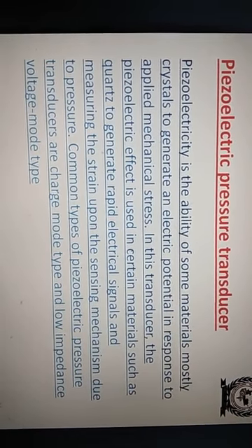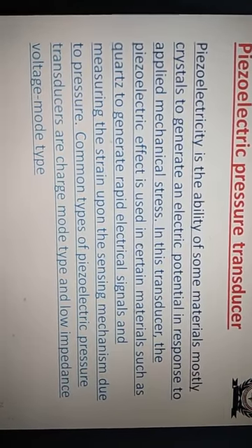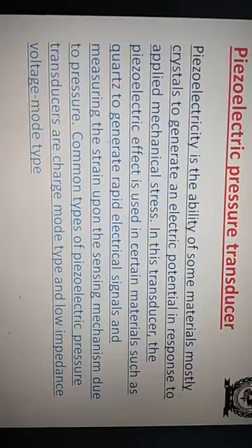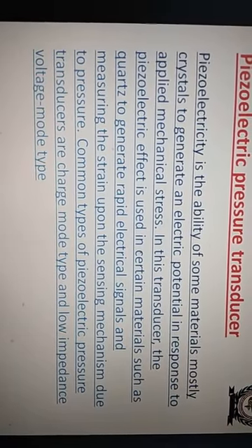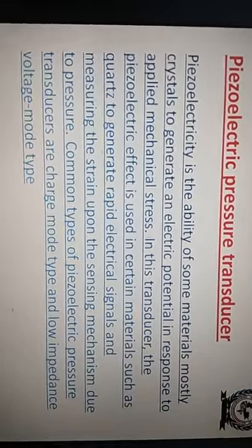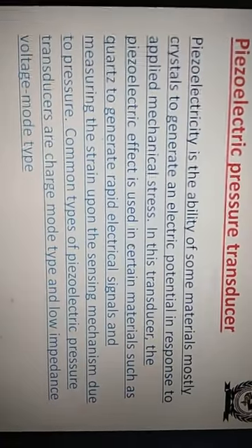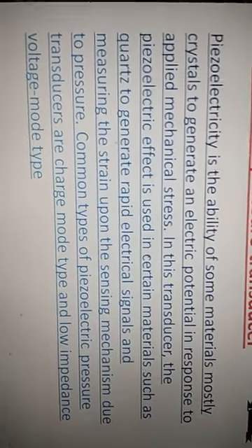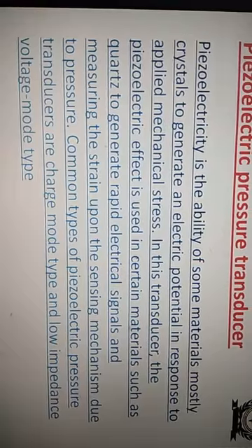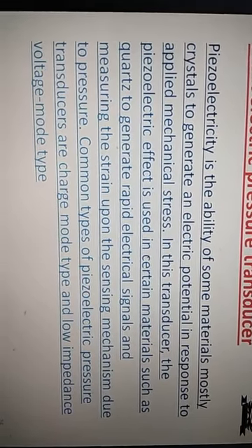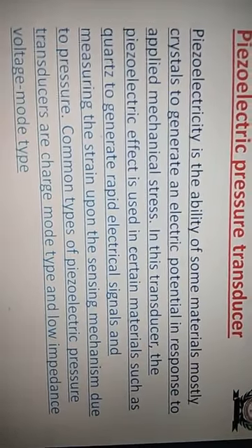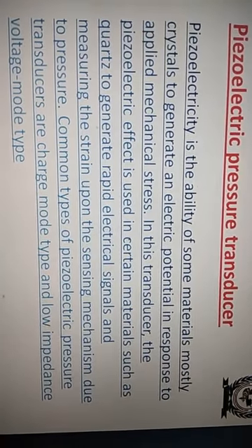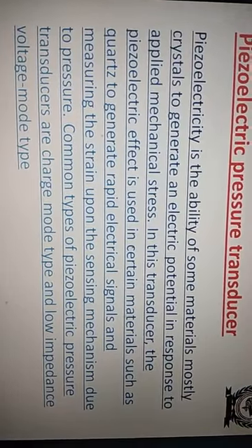Then the piezoelectric pressure transducer. Piezoelectricity is the ability of some materials, mostly crystals, to generate an electric potential in response to applied mechanical stress. You have already heard about piezoelectric crystals, I think. In a similar way, this transducer is used for the measurement of pressure. In this transducer, the piezoelectric effect is used in certain materials such as quartz to generate rapid electrical signals, measuring the strain upon the sensing mechanism due to pressure.